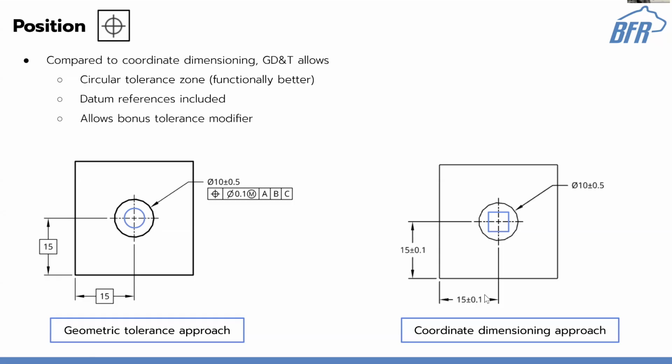But if I'm also off in the lateral direction, now I end up in this corner, which is actually farther away, which might be too much, right? So now I'm accepting parts that otherwise I'd say I don't want. The hole is too far off, but it allows for some more room.